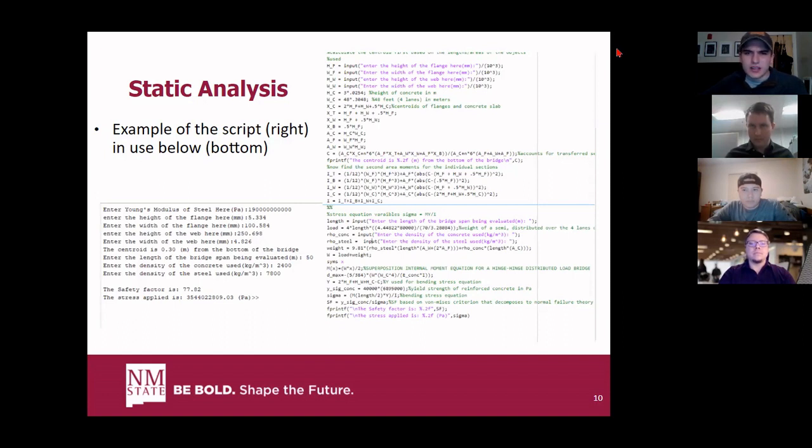And with this script, we were also able to input the different dimensions of the flanges and beams used on the actual structure itself. And so what that was able to do is we were actually able to calculate the safety factor reliably and repeatedly with different components on board. And so going back to what Hunter talked about at the very beginning on using just components off the shelf, we're actually able to go in and just find catalog components and input the parameters of those into the script and basically get the safety factors and weights accounted for that we needed.